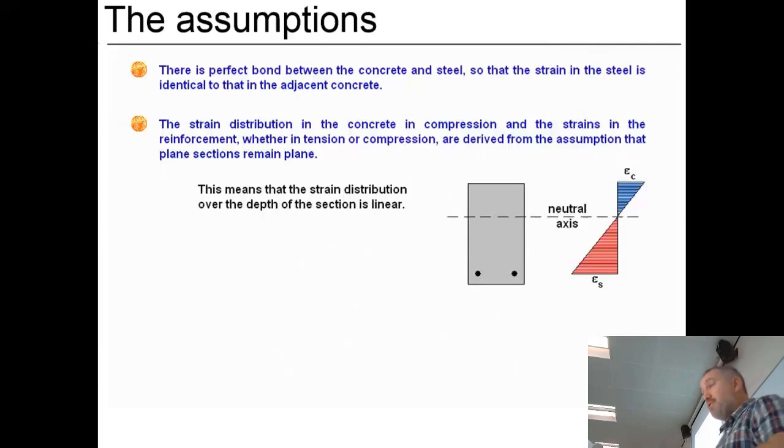So some of the assumptions: this is a 2D diagram of what happens because the steel and the concrete are joined together. The strain will be the same, linear throughout. So you would have seen this diagram before, where above we've got the strain epsilon in the concrete, and these are values that you have to pull out of the Eurocode. At the neutral axis, there's neither compression nor tension, and then that all goes all the way down to the level of the bars, where you've got the strain of the steel.